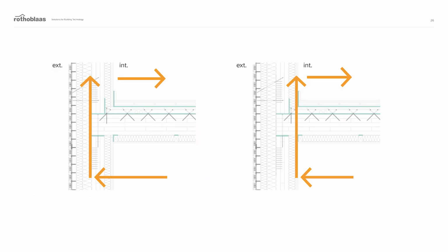In order to have a correct evaluation of the flanking transmission, it's necessary to evaluate properly how the layers coating the walls and the hollow spaces intersect with each other. And here on the slide you have an example. The flanking transmission involves the outer layer of the side structure, which is in direct contact with the source and receiving rooms. So you need to understand how these various elements are connected and fastened. This is where the FLANKSOUND project can be applied.